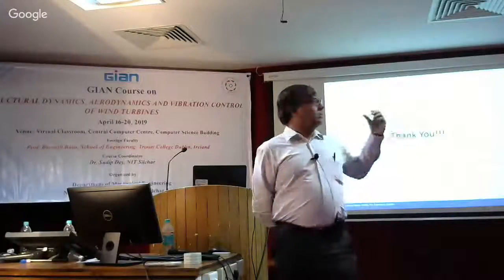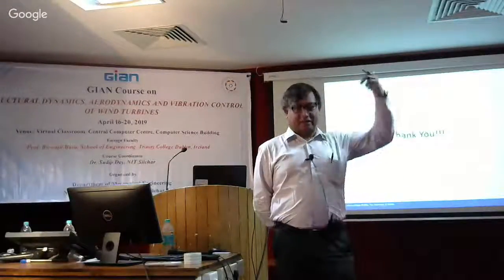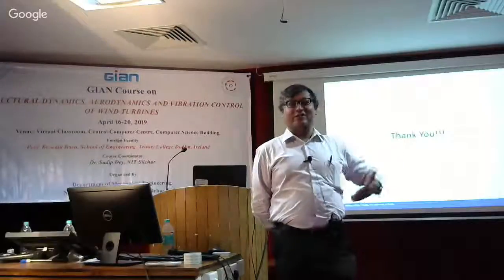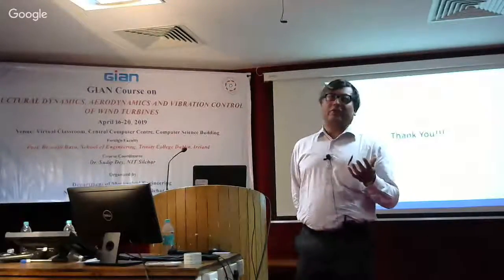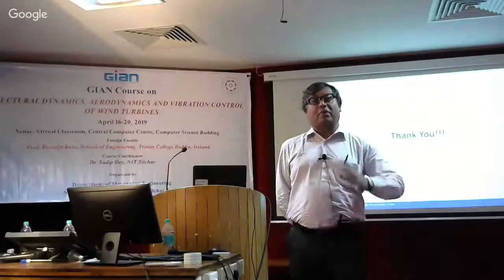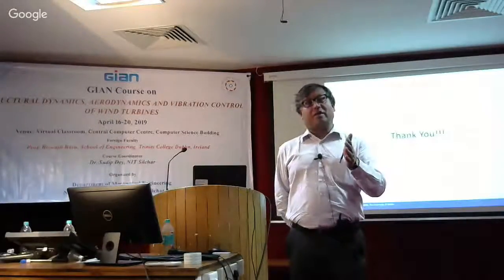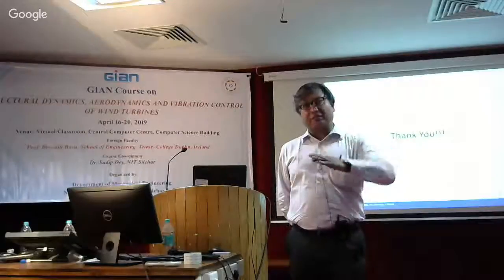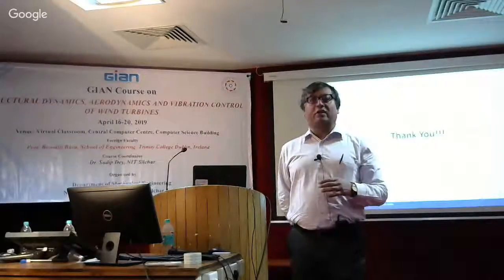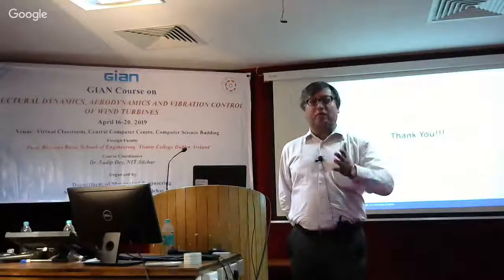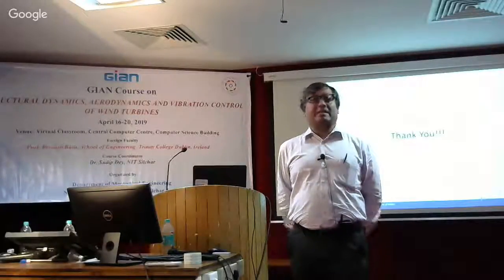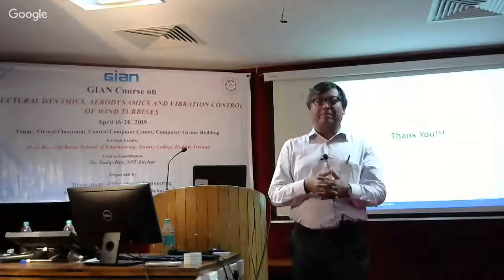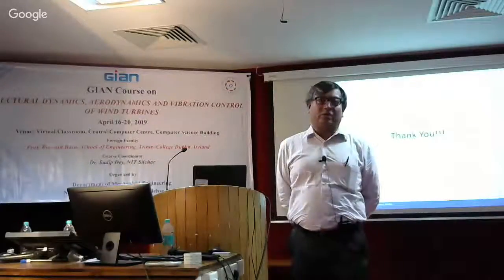No, as I said, pitch control has various functions, the list of things I showed. So it's not just one. It is primarily used for power control, so optimizing power, and then saturating power beyond the rated zone, and then load control if required. But that's just a few to name. There are other things that can be done with pitch control.